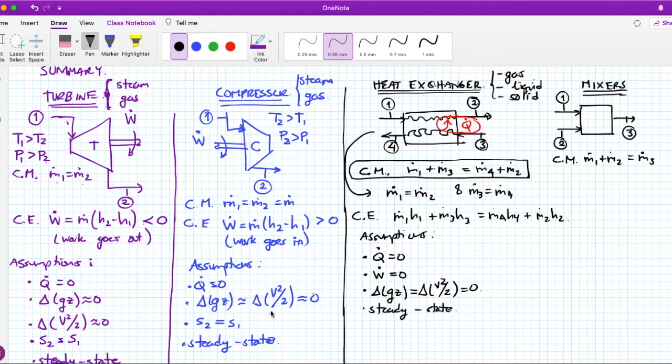Hey, you missed one. You missed that this thing is isentropic. I would say that this is almost never isentropic. I will never say never happens or it always happens, no. But as a general rule, heat exchangers are non-isentropic. So that's one of the basic differences with these other two machines that I left behind, the turbine and the compressor.